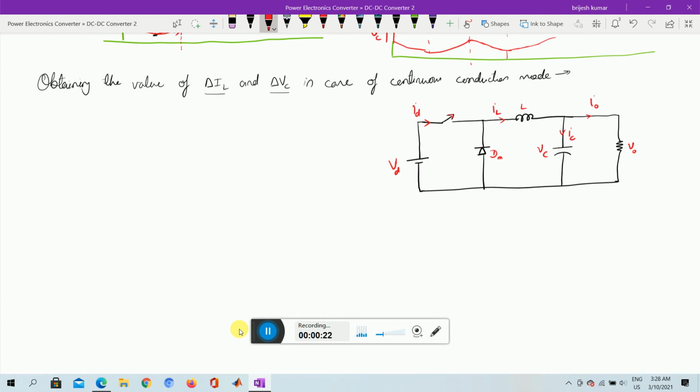The voltage across the capacitor is VC, which is equal to V0. So here we are trying to get the output current as DC as possible, and what we can write here is we can apply the KVL. Let us say the voltage across this is V0. If we apply the KVL, we can also get VL, the voltage across the inductor.